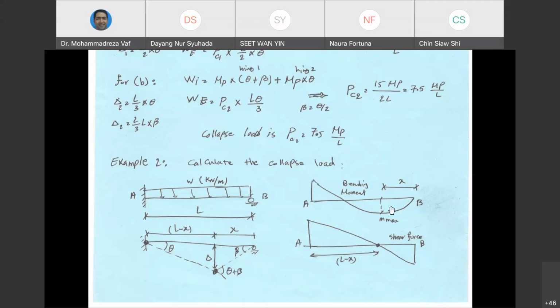If you look at the bending moment diagram of this beam, it's going to look similar to what you see. And the maximum is going to occur somewhere between the moment of 0 and the moment of 0 on the right side. At the beginning of the analysis, we don't know exactly where that maximum is because the force is based on W, not an exact value like 10. So our job is to determine the location of that maximum bending moment, because this is where the second plastic hinge is going to form.